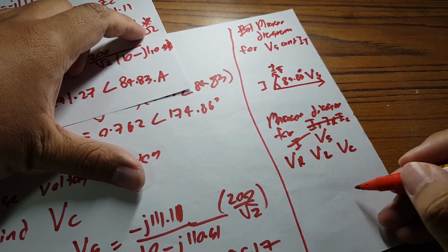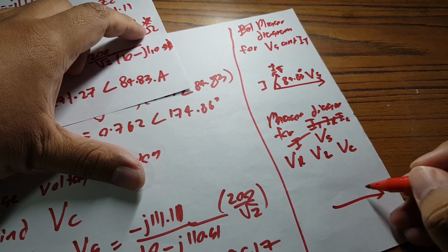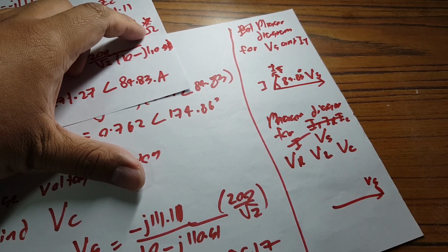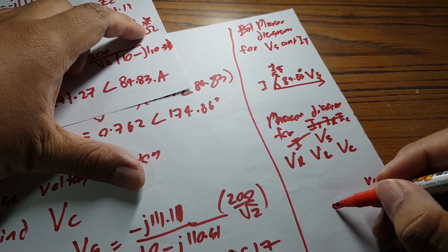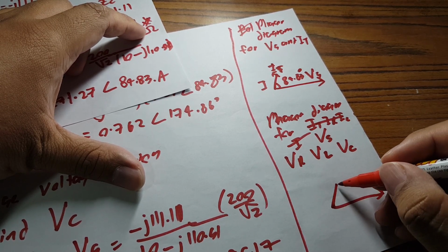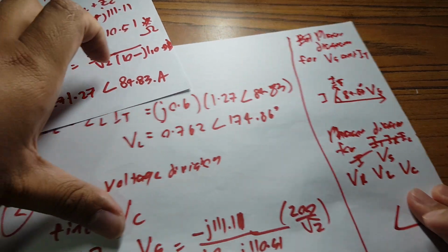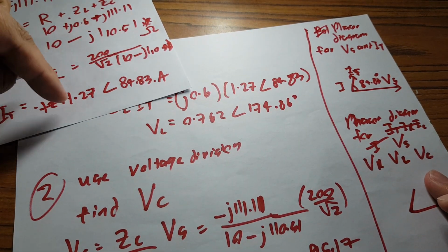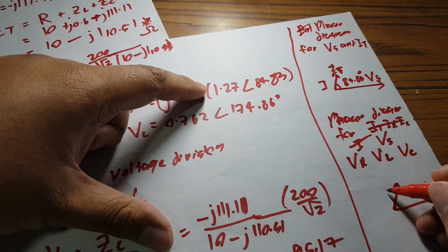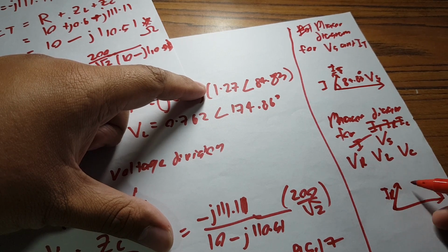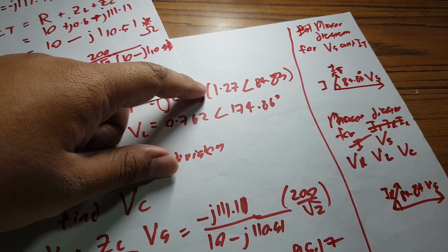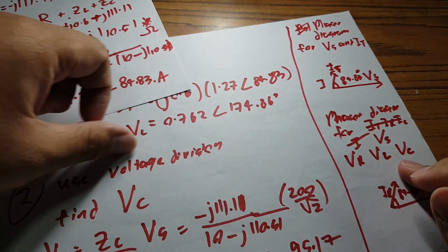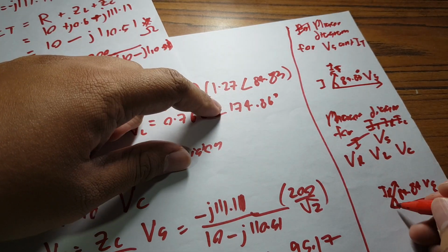If he asks like this, you have to draw the Vs. So Vr is around here, okay, which usually in phase, okay, we don't calculate it, but usually in phase with the I total, IR, okay, so 84.84. So VL, you look at VL is 174.